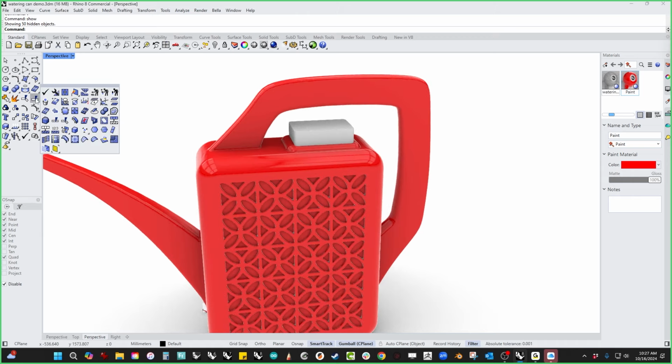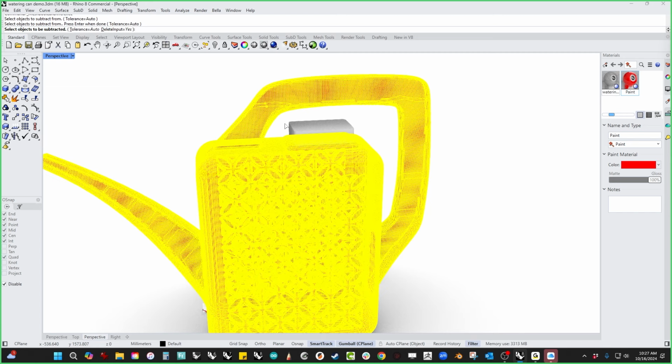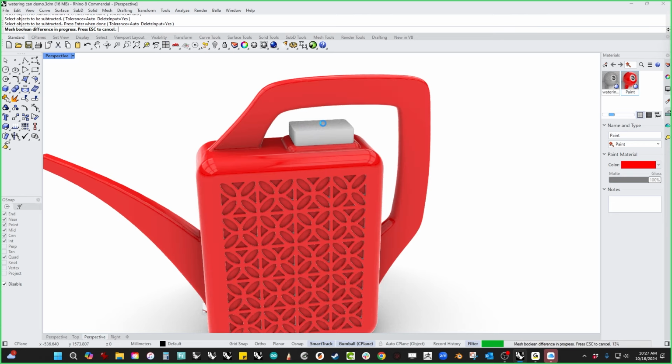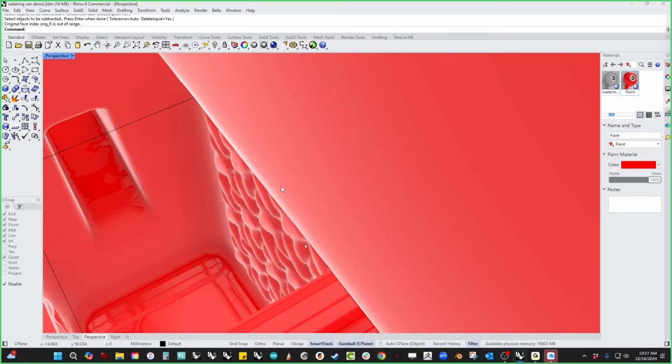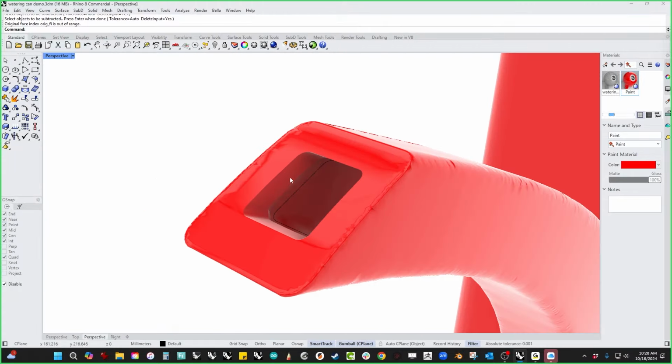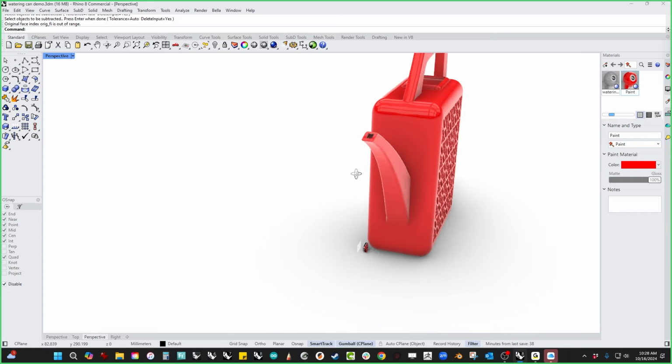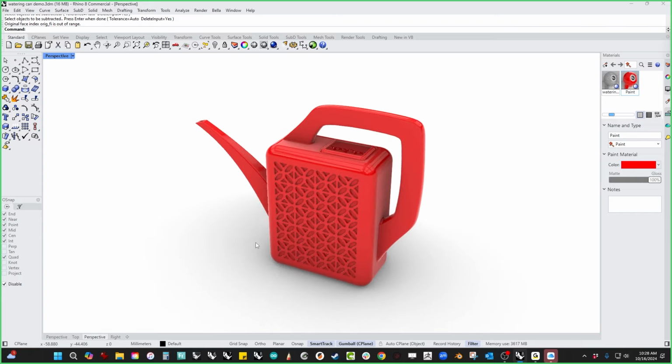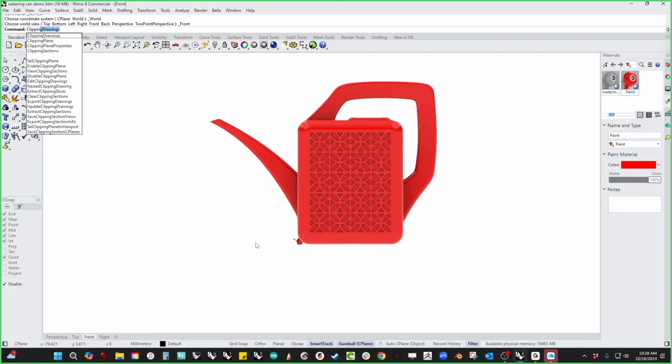And then all we need to do is do a mesh Boolean subtract. That's the part we're using. It's going to think for a second. And the cool thing about this is because shrinkwrap uses voxels, it does a really, really good job of creating usable meshes. And we can see that now this thing is shelled out. That's not ideal. We'd probably do a better version of that. But you can see if I grab this and do a clipping plane.